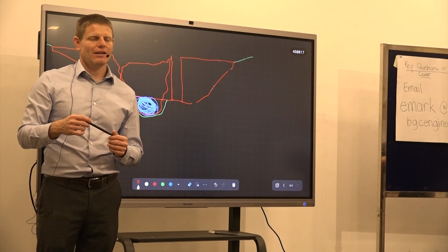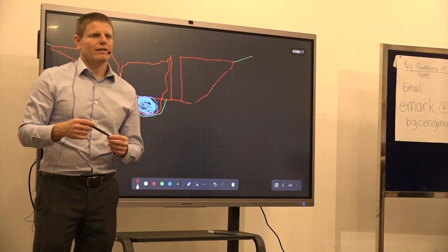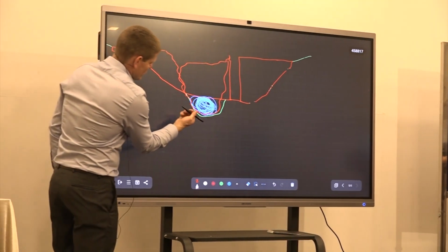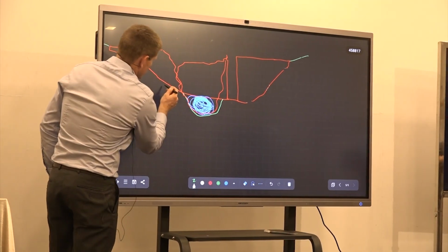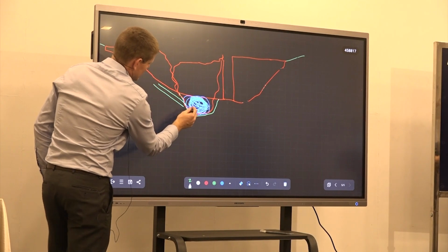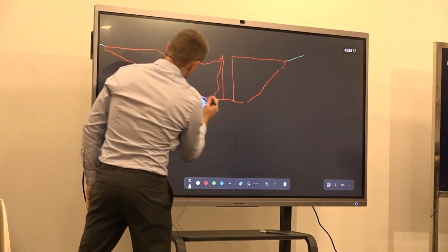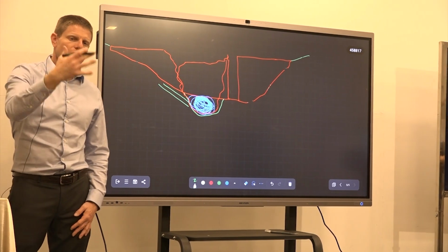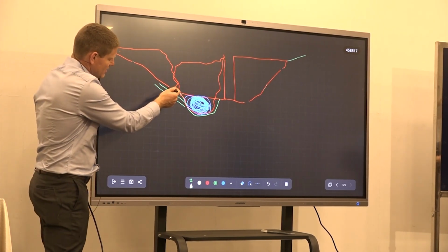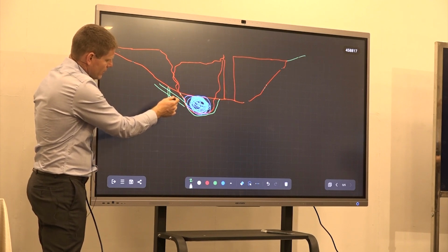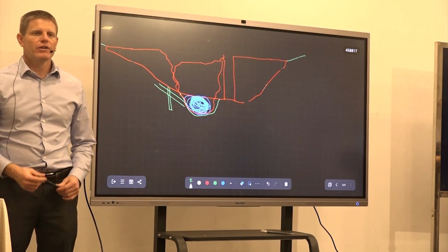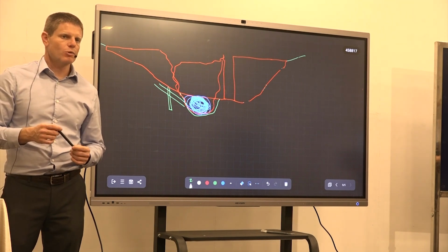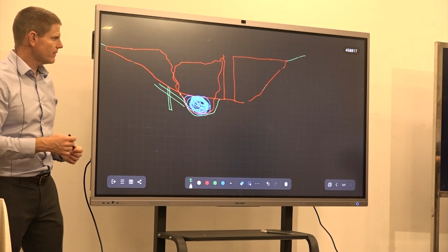The geology of the dam site. Yeah, that's right. So maybe we decide, well, if the bedrock structure was very poor, maybe there was a bedrock structure like this that allowed or facilitated this failure, you could go and do an investigation of the bedrock, maybe some boreholes and core samples to try to understand if it's possible for the bedrock to fail into this opening. So this is an outcome that you could have.